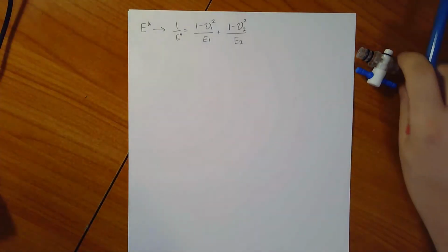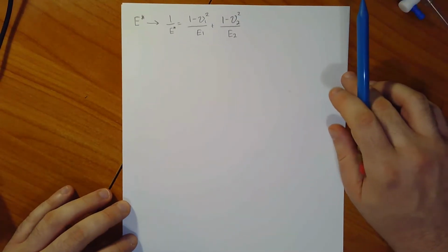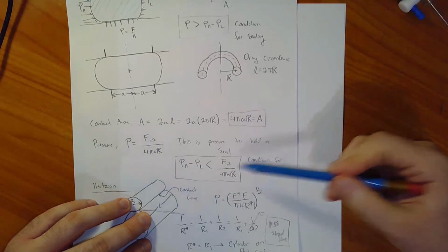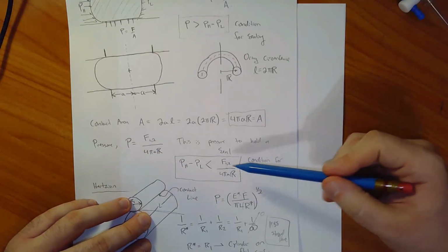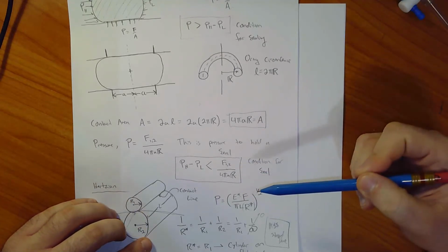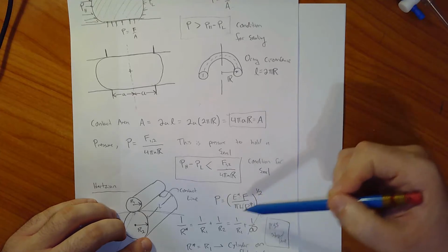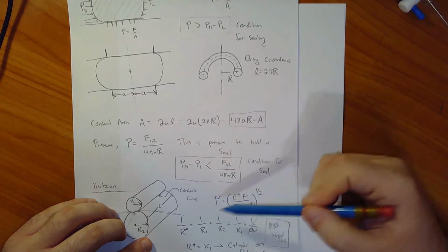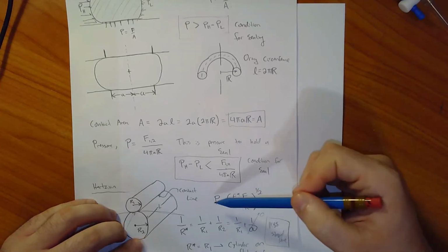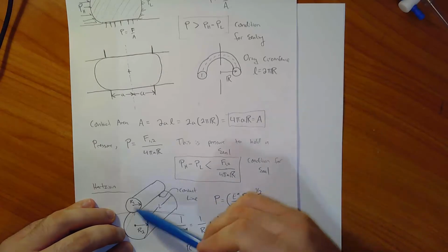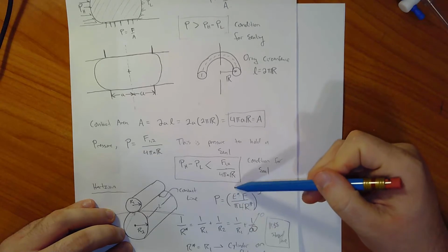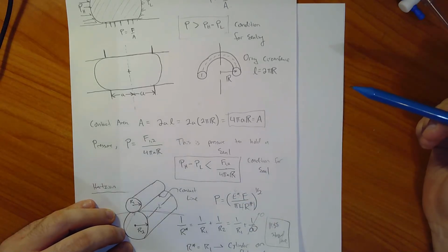So the whole point of this is to run through and convert a number of things from this expression for the seal to function correctly that I don't know, right? I don't know things about the force, and I don't know things about the pressure, so I'm going to try to put those pieces in to get an expression here that gives me finally the value of the pressure in that space, which will tell me whether the O-ring is sealed or not. So this is just something that I can now stick in for E star that I now know.